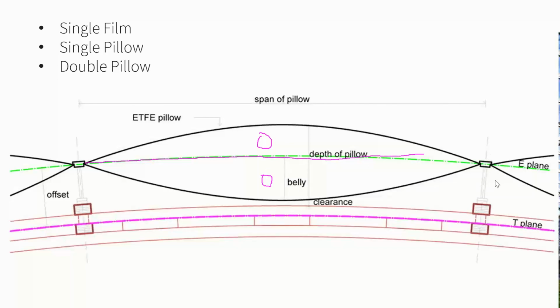But really looking at this, where's going to be your critical area where condensation can occur? Really, it's at each of these frames, right? These pillows need to be pinched in, the films need to be pinched in, and it comes down to a spot where essentially you have almost no thermal insulation at the point where these two films meet. So how much risk is that? And is there enough heating from, say, the framing around it to keep that warm enough?